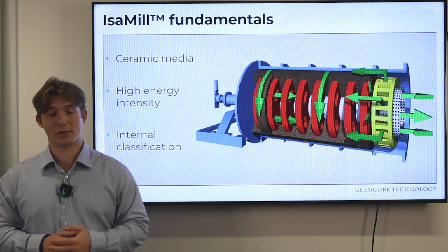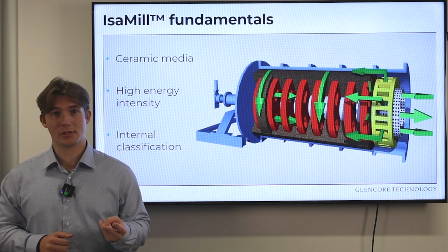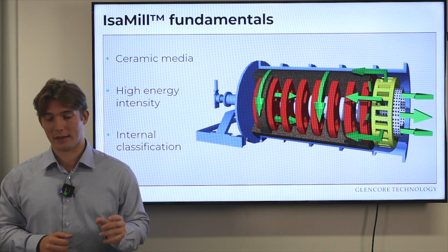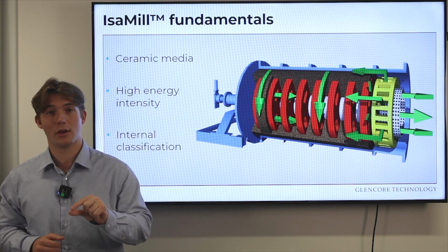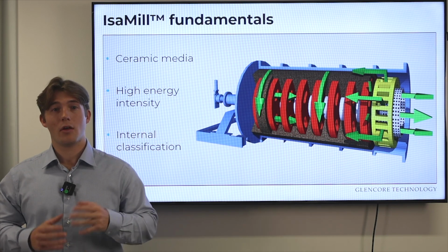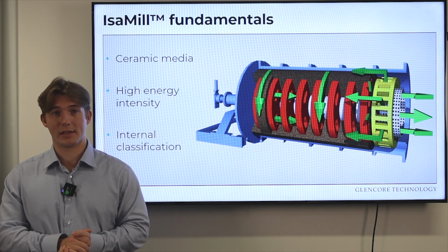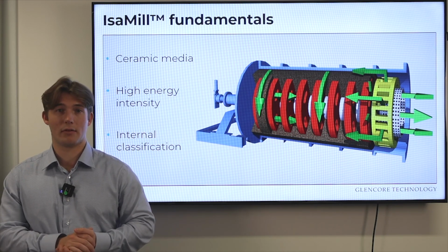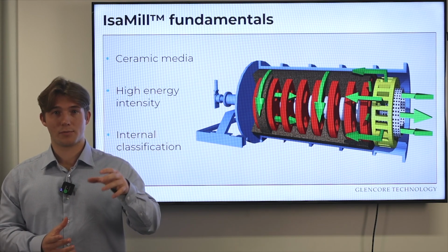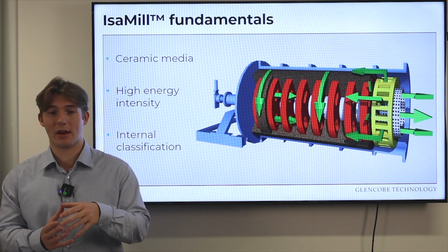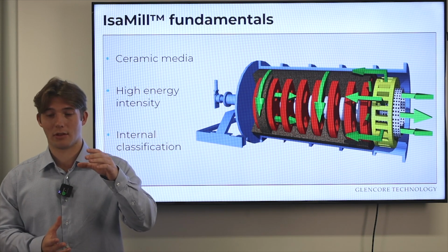What you'll notice is the spacing between each of the discs is a lot smaller in the last disc when you look at the relative position of the last disc to the rotor product separator. This smaller spacing is deliberate to allow for more centrifugation to the outside of the mill, which pushes all the media and slurry in the area out to the shell of the mill.